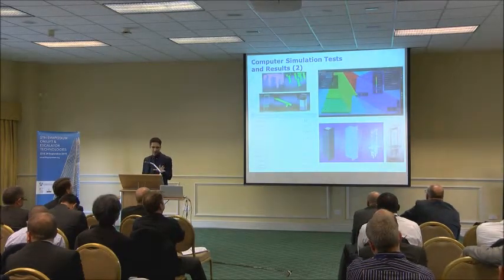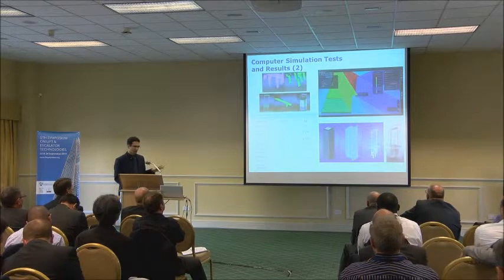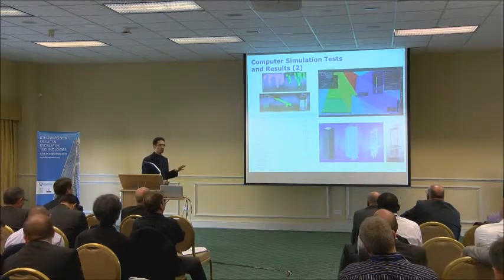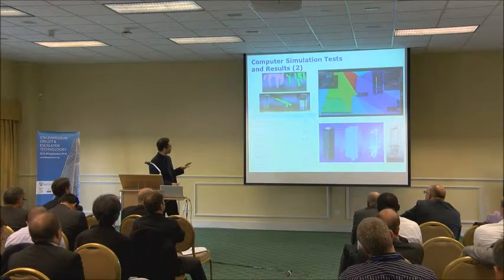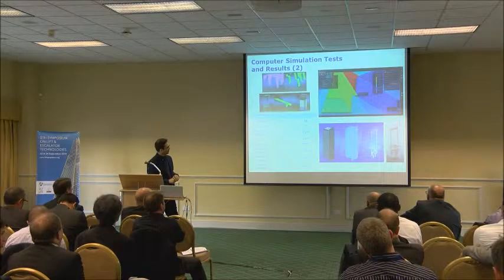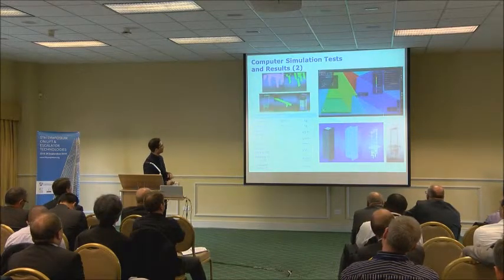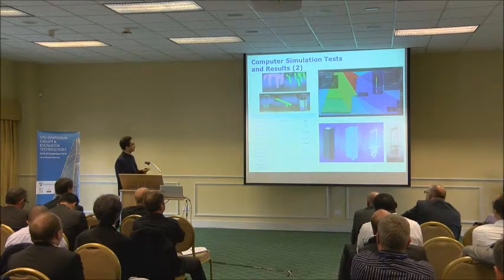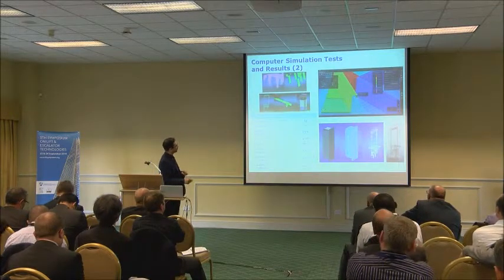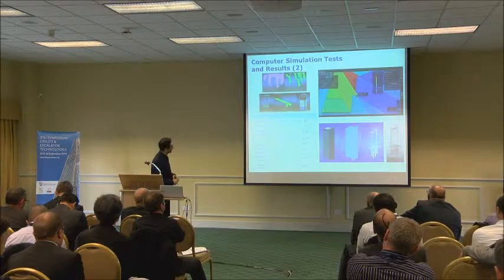We use a variety of coding, modeling, and different software to be able to adjust it, because one of the most important and hardest points in my experience was the small components inside the actual elevator and lift model itself. To do that, I needed to simplify quite a few meshing elements and go to a very small element size to be able to fit them into our software.